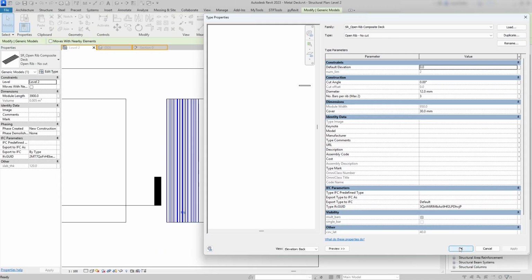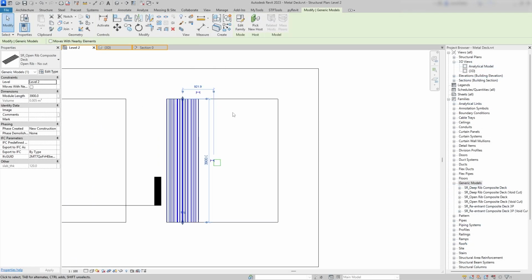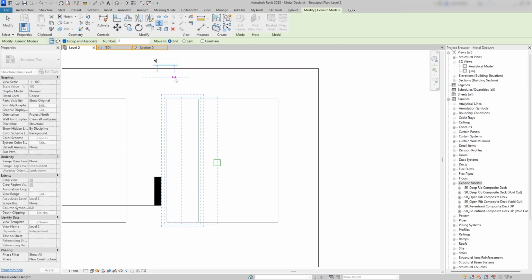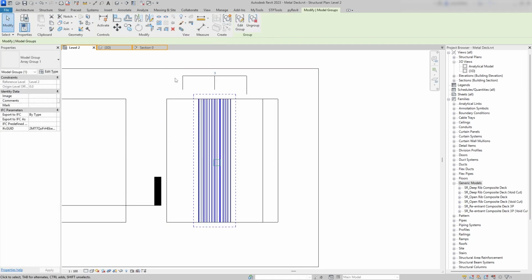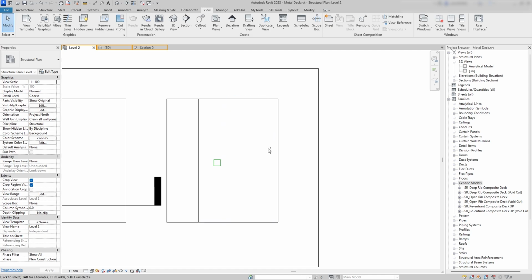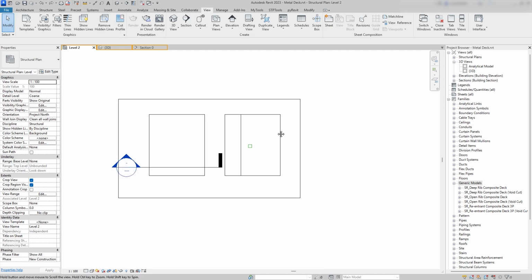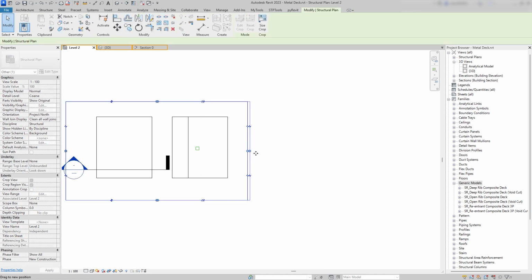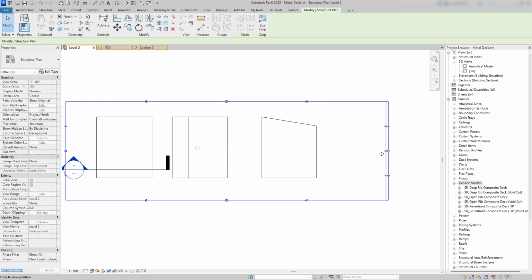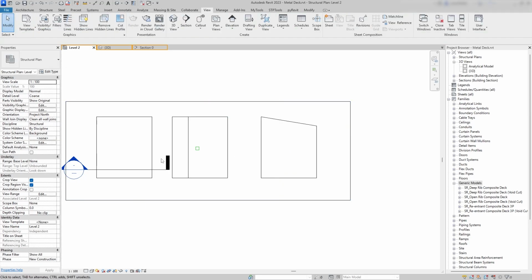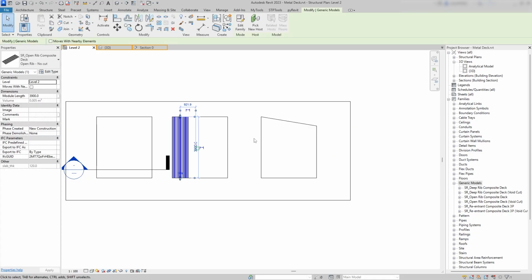If you are dealing with a simple square slab requiring no adjustments, you can simply create an array using the module width as the spacing interval. However, such straightforward cases are rare. We often encounter openings for staircases, and in some instances, the slab is not oriented at a 90-degree angle. Therefore, it is best to model the panels individually in these situations.